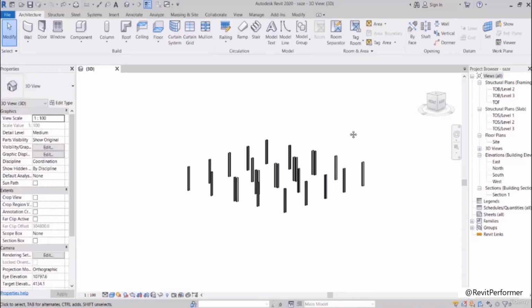The next thing is project management. For example, in Navis, you can have a code that this is built floor by floor. But if you draw it flatly, suddenly all of the floors are built together. If you draw your columns flatly and you want to do the simulation in Navis, it's not built floor by floor. Suddenly it appears as all of the floors. But we can use these two strategies only when the section of the columns does not change, right?